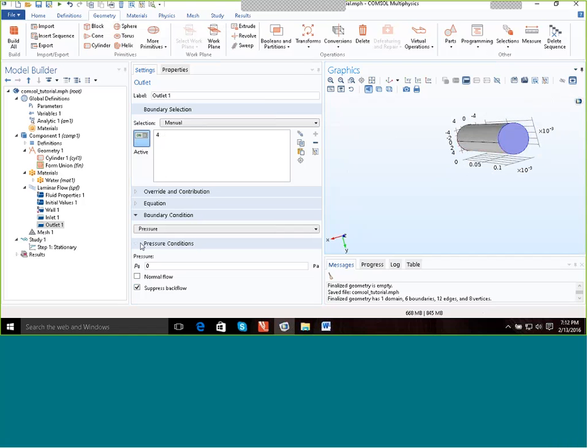Okay. And there's various things to do at the outlet. We are going to give it a pressure, and I think the problem says the outlet pressure is 1 atmosphere, meaning it exits to the atmosphere. So if I redefine the pressure as gauge pressure, which I'm free to do because the only thing that's relevant are pressure changes, I can actually leave the pressure here at 0, meaning it's zero gauge pressure at the outlet. I do have other options for the outlet. I can specify velocity or something, but the problem statement was that the outlet was at a fixed pressure, and in fact it's going to be zero pressure. I'll say that these pressures are gauge pressures.